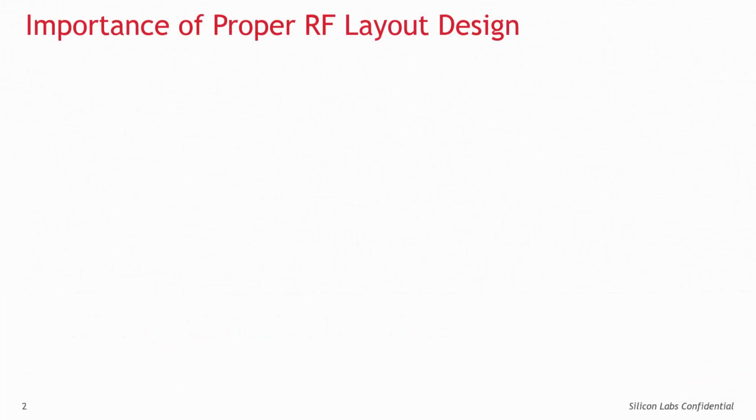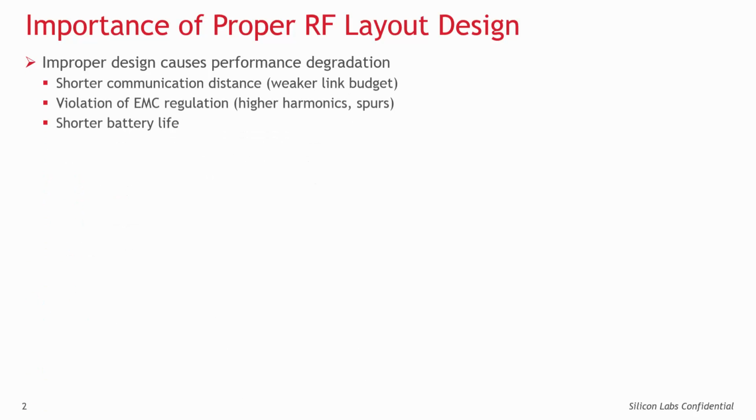First, we should discuss why the proper layout design is important for these units. It is important since it affects the RF performance of the unit. If the layout is designed incorrectly, that can cause degradation in the communication distance, the unit can violate the relevant EMC regulation, and even the battery life can be reduced.